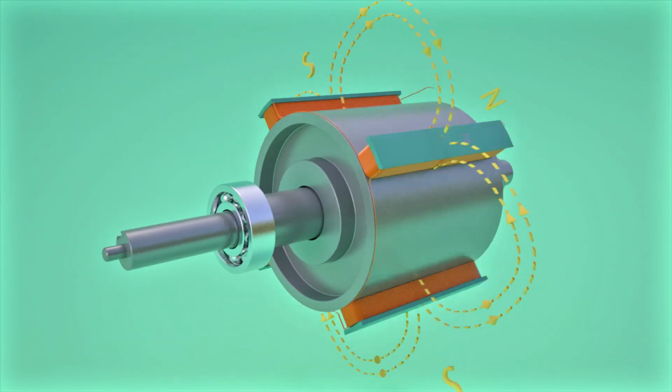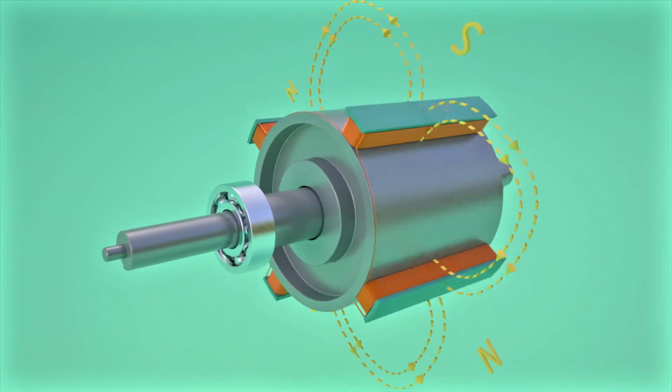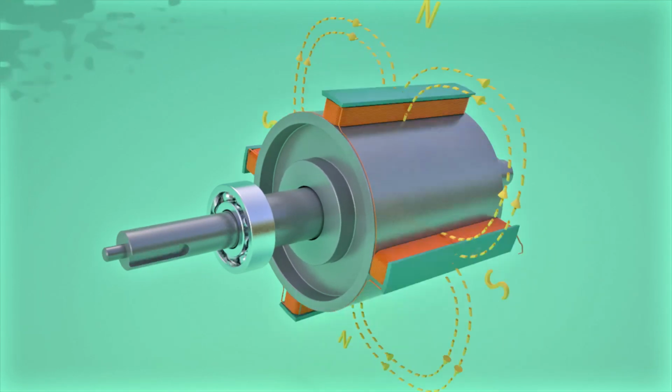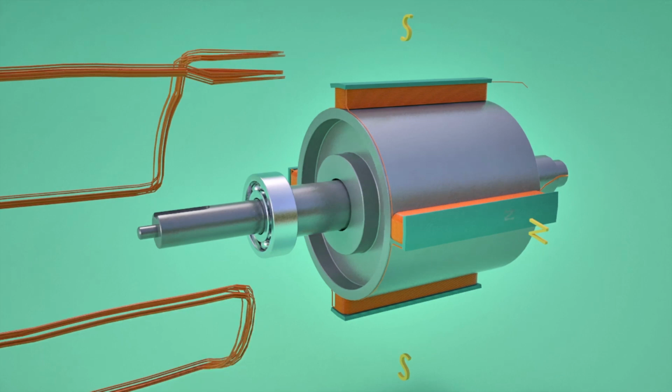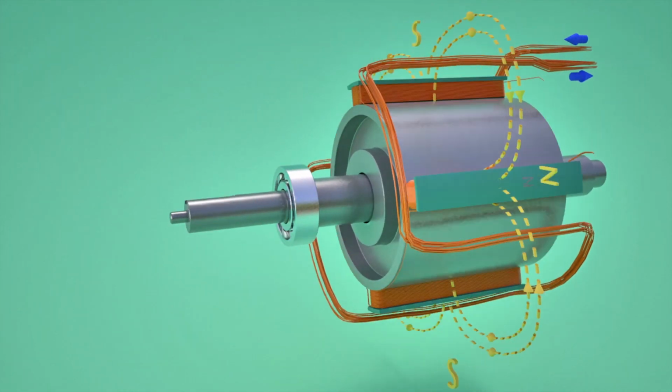The rotor is made to rotate using the shaft. This makes the rotor flux also rotate along with it, at the same speed. Such revolving magnetic flux now intersects the armature coils, which is fitted around the rotor. This will generate an alternating EMF across the winding.